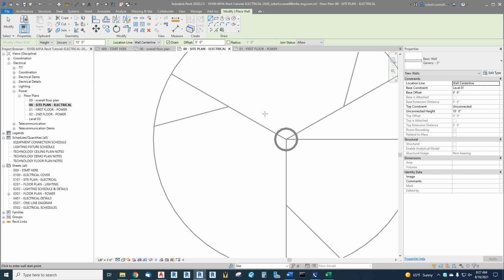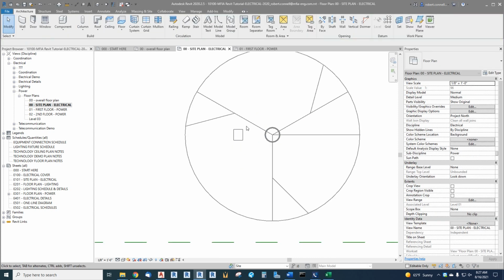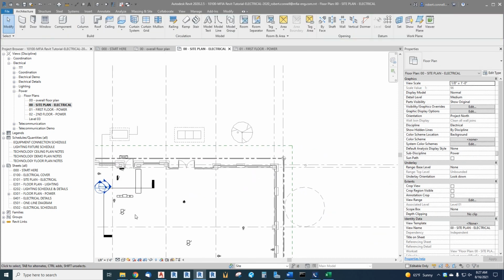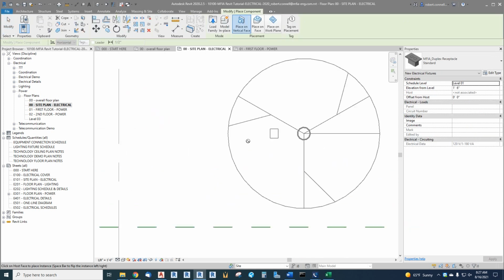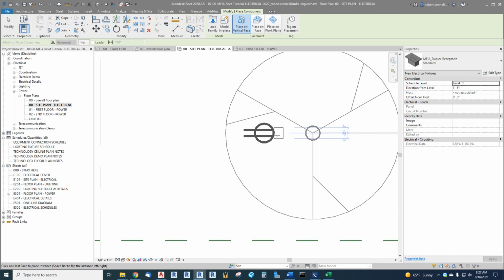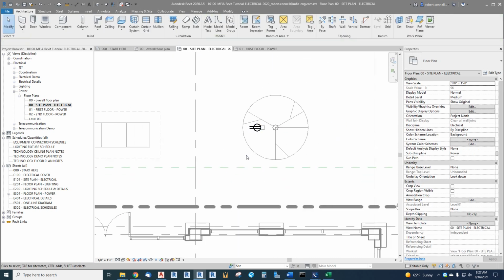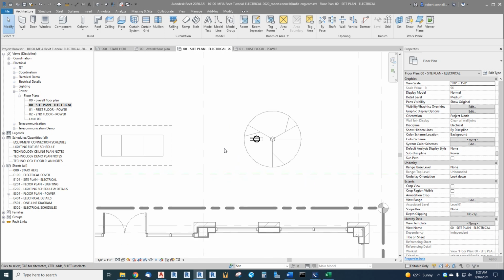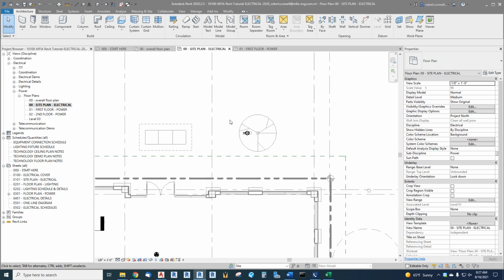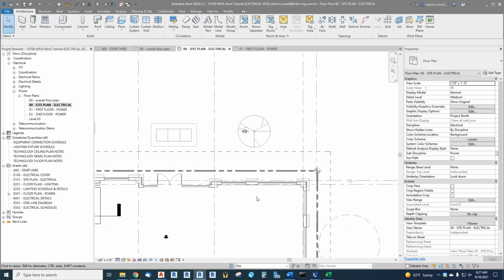Let's say if there's like a tree well here. I'm going to put a short little wall, let's say just like that. And now I can take my receptacle, create similar, drag it over, and it finds the wall. So that's a way to cheat a wall into the system to let you mount receptacles. You may find that sometimes even inside when you want to put a receptacle on an island that's just lines, you can build a wall.